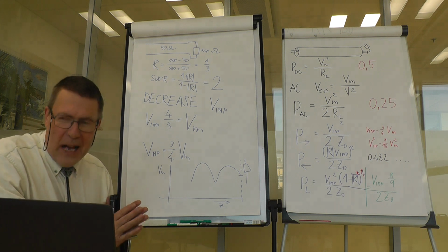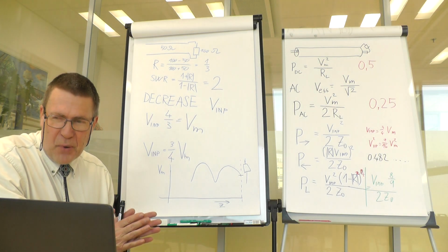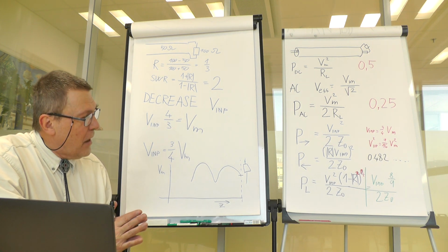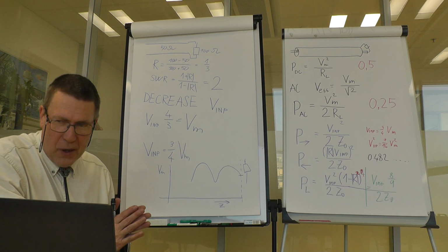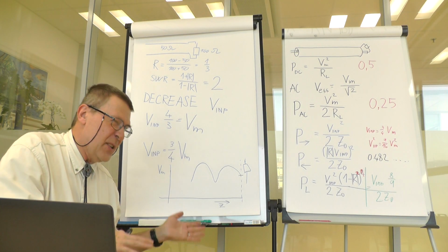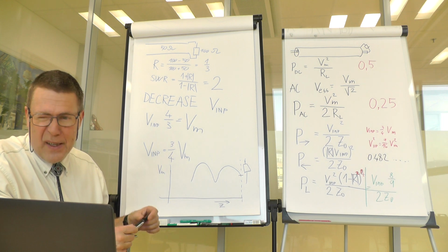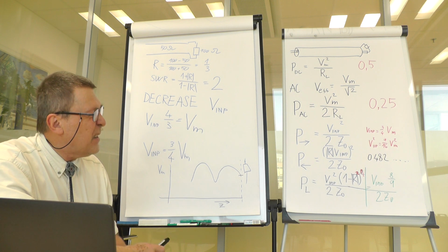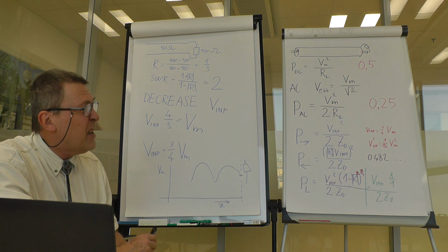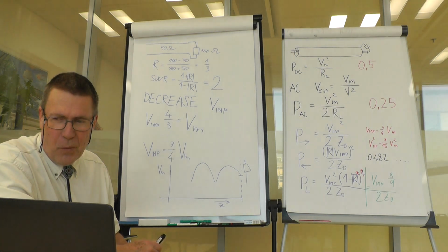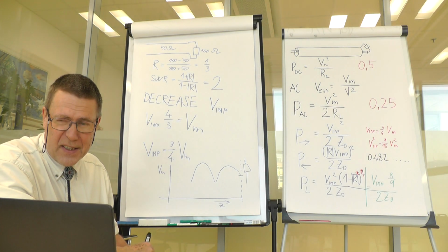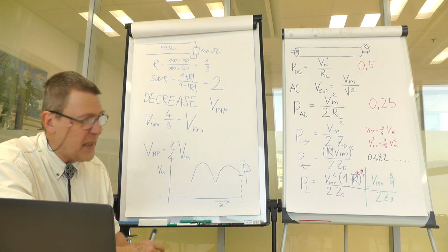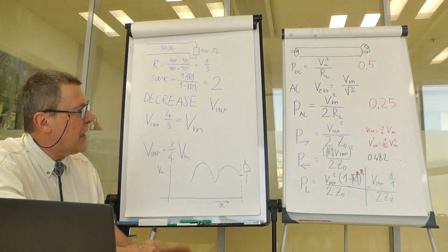So this is the result, that any mismatch, that is any reflection on a transmission line, makes problems to radio engineers. And this is not the only case, because in fact power is not that important, well, unless you heat dry wood or heat food in a microwave oven, then you have of course an important story with the power. But much more important is information, and any reflection causes distraction of the information that is carried by the electromagnetic wave. But that's another story.